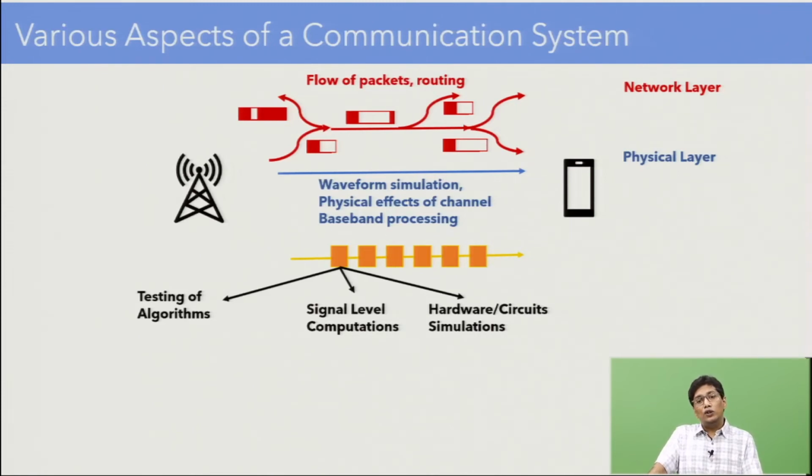So, in that case we can simulate each block separately, see if they are working or not, and just abstract their performance and use that for a larger system. For example, if I know that a particular filter creates this output waveform given this input waveform, then I just use that relation to test the algorithms. I do not have to actually simulate the whole block again, because it would probably give the same result.